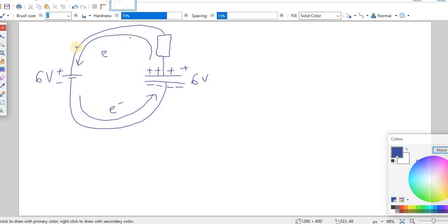So the electrons are flowing like this, but they don't go through this, because here we have the dielectric material. Remember, the word is dielectric material, which is an insulator. So the charge doesn't flow through this. So the charges go like this, they accumulate here. So this plate gets positively charged, and this plate gets negatively charged, until the capacitor becomes fully charged, depending on the potential difference, or EMF, or terminal potential difference of the cell. So that's how a capacitor is getting charged.